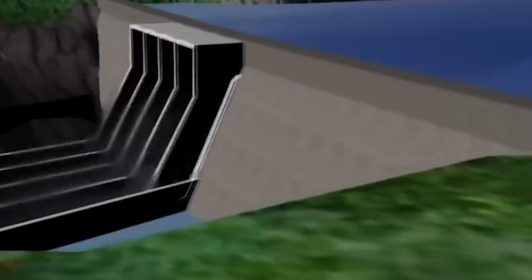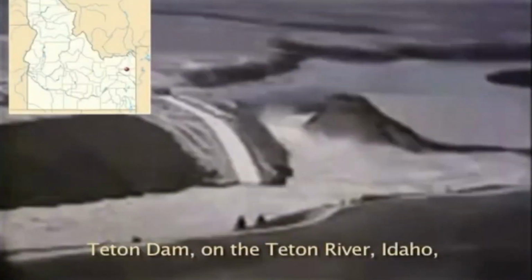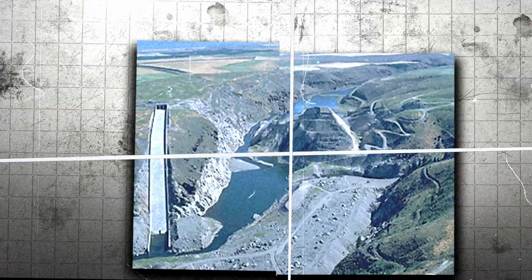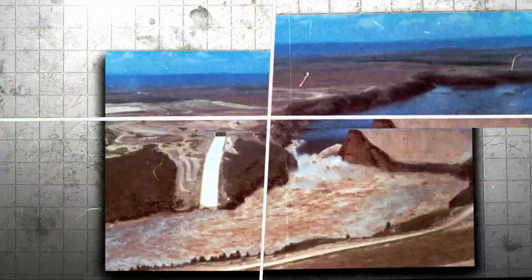Now, having talked about all this, there have still been times where dams failed because of seepage. And as promised, let's look at a couple of big ones. One famous dam failure was the Teton Dam in 1976, which is in Idaho. This was a massive earthen embankment that failed just as it was being put into use for the first time. Engineers later found out that the soil under the dam had lots of holes and gaps, so a lot of seepage was flowing under the dam.